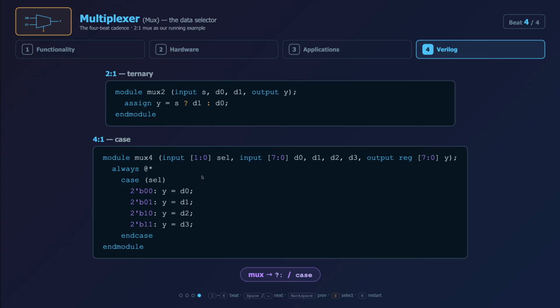All right, I also wanted to show you a use case that I think is actually even more instructive, and that's a 4-to-1 mux Verilog description. Okay, so in this particular case, because it's 4-to-1, the select line needs two select lines so I can get all the different 4 cases. And then I wanted to show that you can use multi-bit data vectors. Okay, so D0, D1, D2, and D3 are now 8-bit vectors, and that means the output has to match. So the output is an 8-bit vector. So the 7 down to 0, that's 8 positions. That's what tells you the size of this multiplexer.